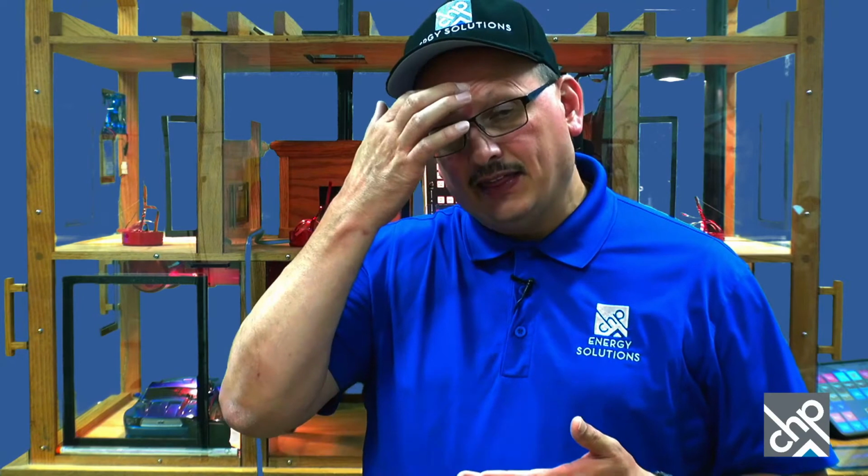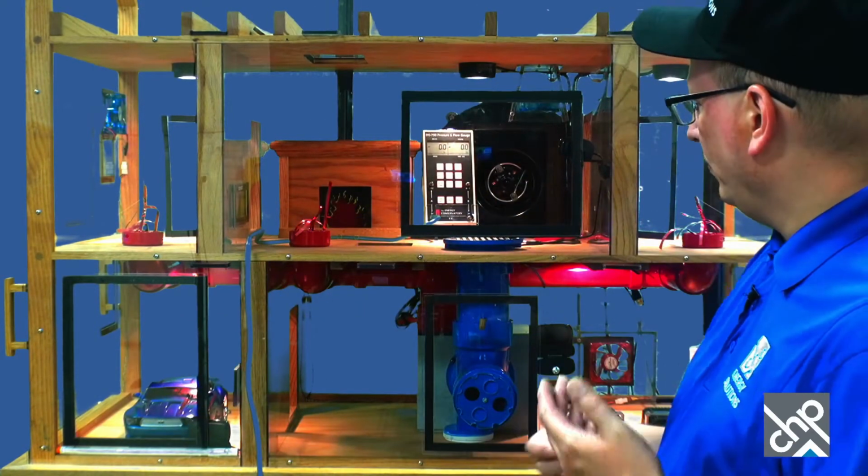And sometimes you get a trick, like an attic fan or something that's on, and it'll be messing with you because it's in the summer and it's set on a temperature. And if you have leaks between the attic and the house, it can be affecting the pressures in the building. So if you're getting something weird, and I've had that happen before, I kept getting a really high baseline, and it was really strange, and come to find out it had gotten hot enough to turn on an attic fan with a temperature sensor, and there were a lot of leaks between the house and the attic, and that was affecting my baseline. So I had to go up and disconnect that. It was easy to get to. But anyway, baseline's important.